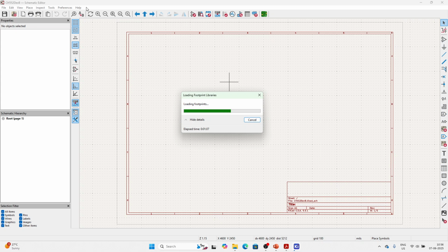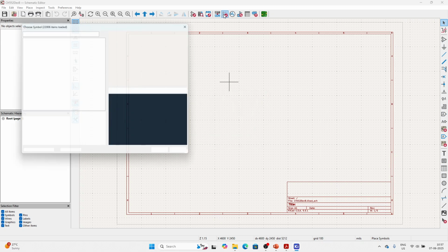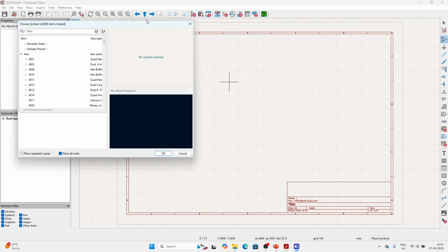Then moving things sideways, upward, mirroring, flipping. Then comes your other set of icons, which are on your editors: pin editor, searching of components, labeling of components, ERC check, electrical rule check, whether all things are correctly mapped or not. We can go over each.